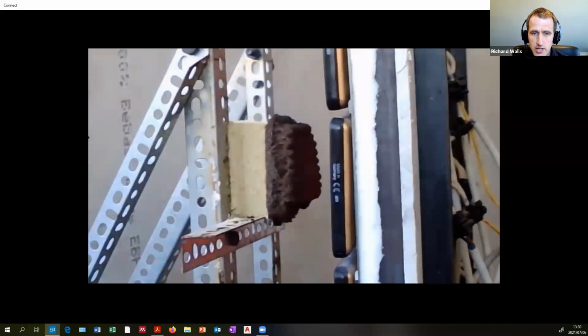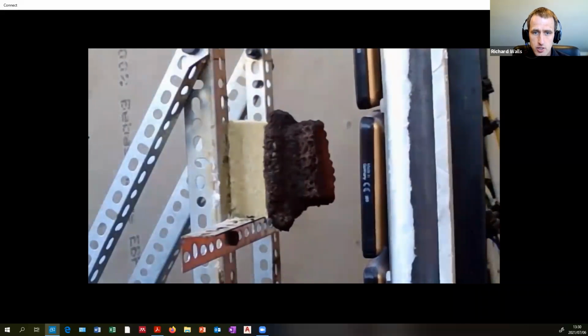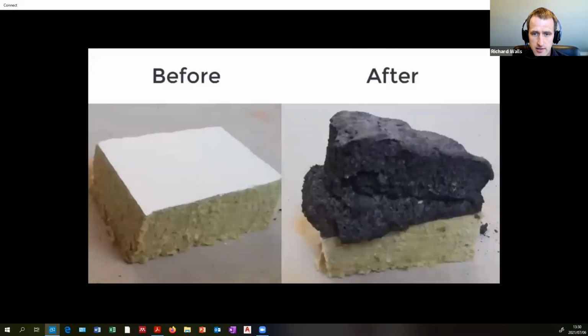This is then for closing your bigger penetrations. You've got a non-combustible substrate and an intumescent on top. And then you can just see how it grows as it's heated up. And this is, if you've got a penetration, it's like a putty. So there's a plastic box and you put a putty on the inside, and then it protects the plastic box from melting.